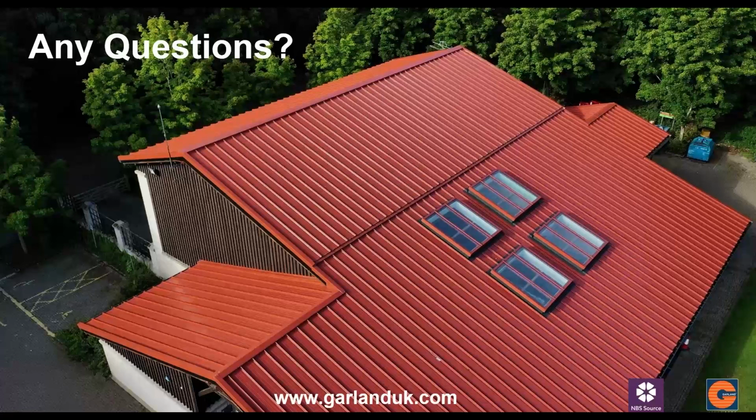So a lot of the roofing membranes or roofing substrates on the market today will be tested to B-Roof T4. And you'll see in Part B of the approved documents that if you're immediately adjacent to a building, you'll be looking for a B-Roof T4 system, and this slightly changes depending on the adjacencies, which I'm sure you guys have seen or read up on before.